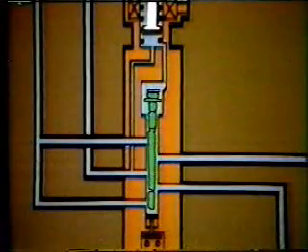Let's take a closer look at the actuation sequence. An electrical impulse is received by the solenoid when the engine reaches approximately 66% speed. When the starter drops out, the solenoid retracts, causing the spool in the control valve to shuttle. Lube oil pressure can now flow through the lines to the actuator.